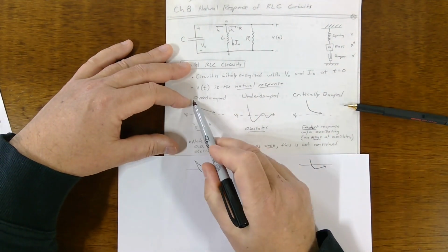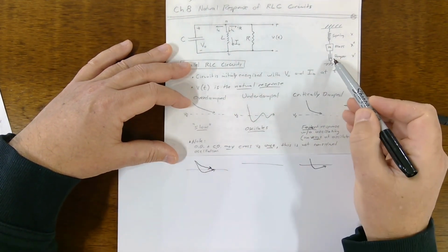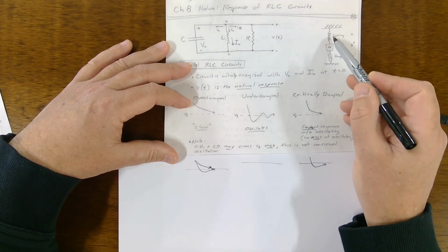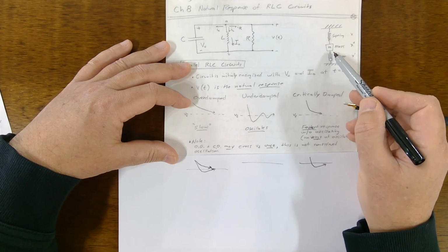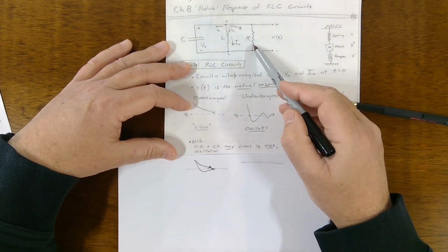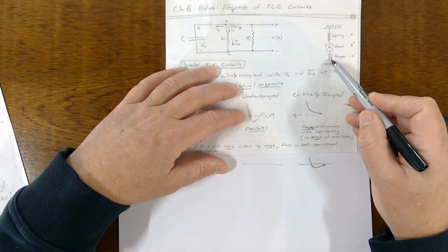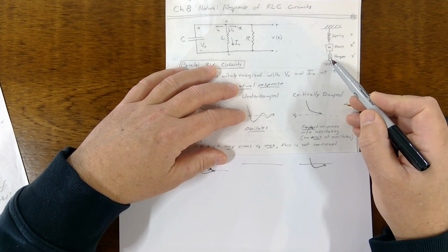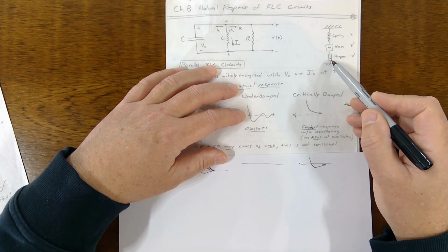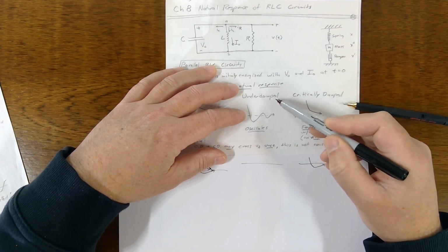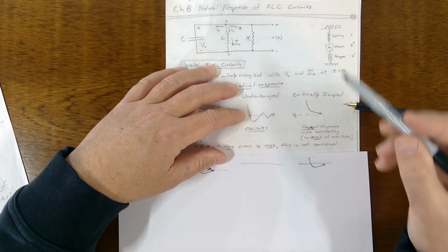Basically, if it goes down really, really slow, there's too much damping. Like imagine there was molasses in here, and you pulled the spring up, it would go down really, really slow. That's overdamped. So if you have a high resistance, you're going to get an overdamped circuit. If there's air in here, or your shocks in your car are bad, all the oil has leaked out of your shocks, and you push down on your car, it's going to bounce. So that's underdamped. Okay, a low resistance value will lead to that.